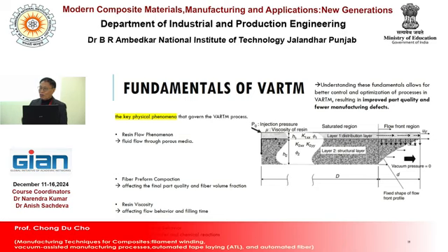Because differently from RTM, hand layup or autoclave, VARTM has many variations, such as thickness variation or dimensional variation. That means more trial and error is needed without good experience in advance or simulation.